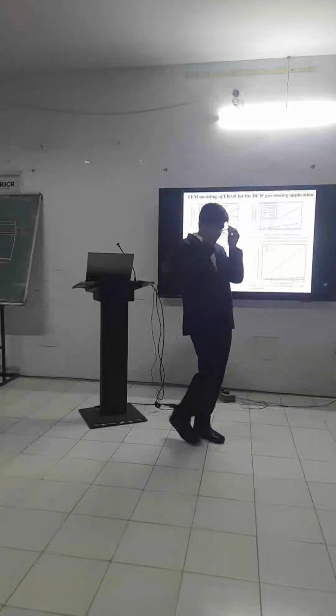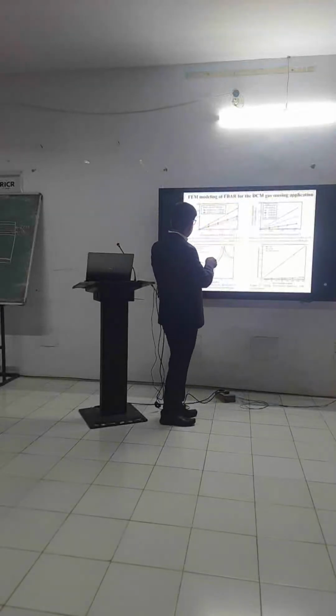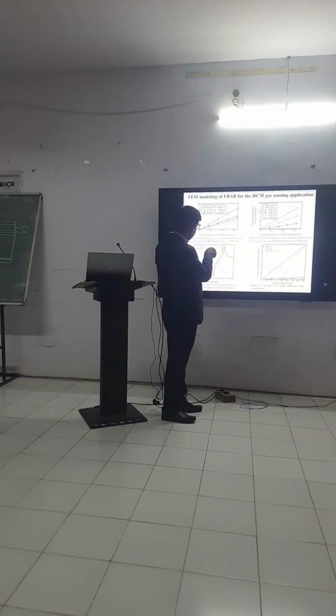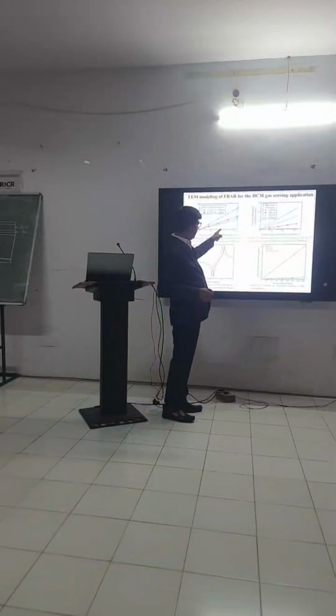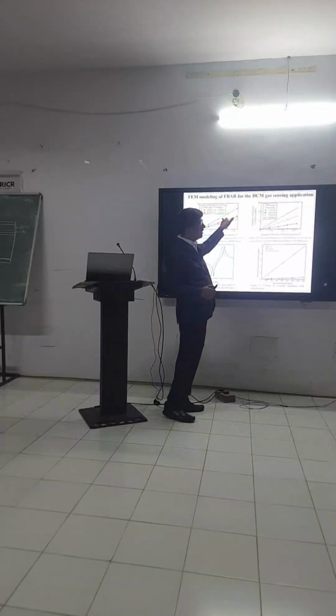Understood? So see here. There is a change in the frequency, and here you have a change in the concentration. So for example, you have a concentration of 50. Here the concentrations are 50, 100 and 150 ppm. Then what will happen? This 0.7 micron thickness nano sensor will give you the highest change in the frequency. Why? Because its frequency is high.